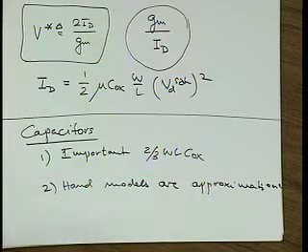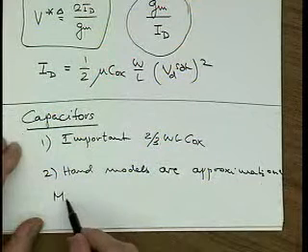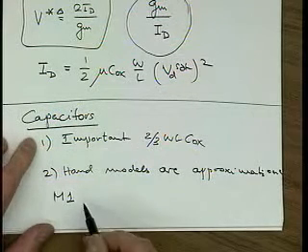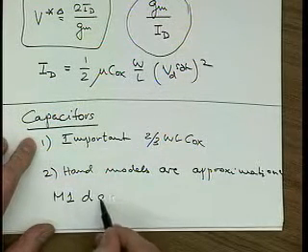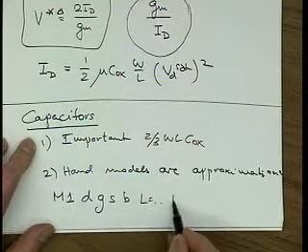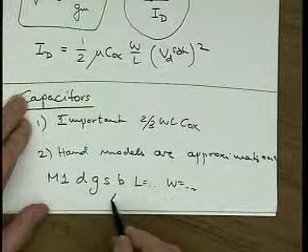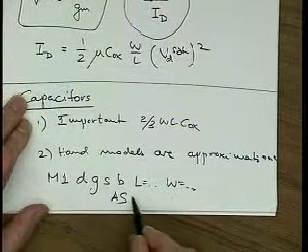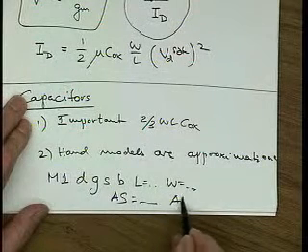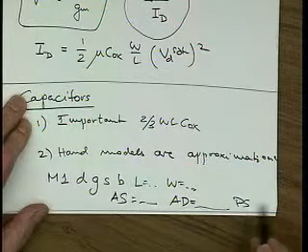And if you don't want to calculate them by hand, which is a little bit tedious, then do yourselves the favor that if you define a transistor in SPICE, right, and then what is it? Drain, gate, source, bulk, and then L something, W something, right? And then also specify a source area equals a drain area equals something, and same thing for P, the perimeter of the source.